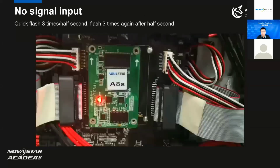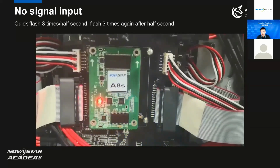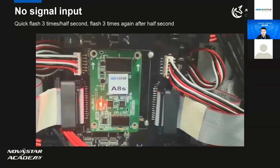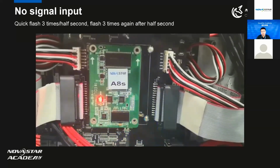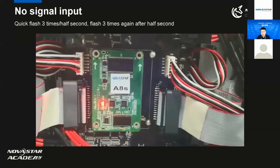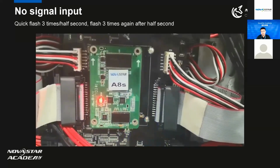Okay, this is the final one. Usually in our LED control system, we will feed HDMI or DVI or SDI, a lot of different video sources. But if the video signal is not fed to your system successfully, you will see the receiving card indicators flashing like this.